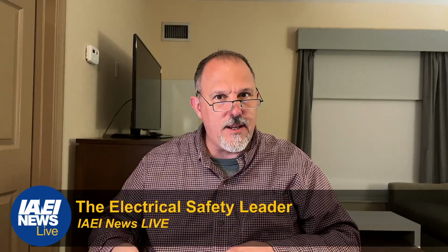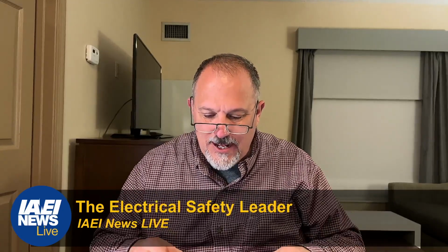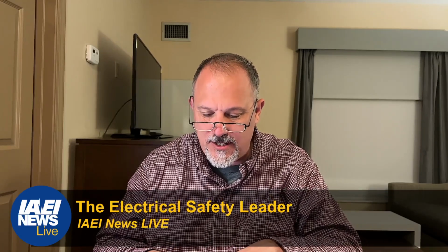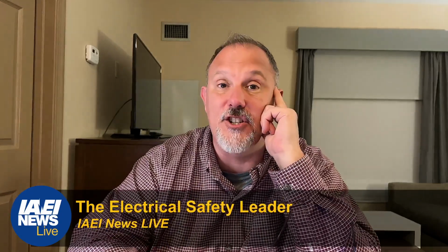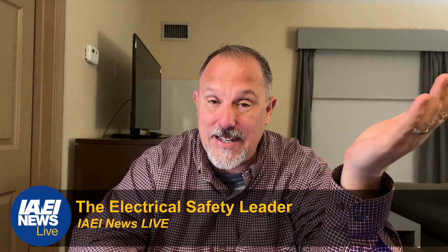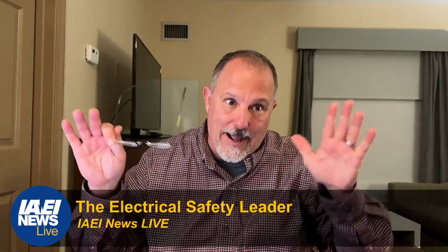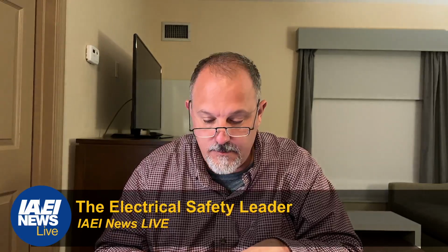Oh, this is interesting. If equipment supplied by an outlet covered under the requirements of this section is replaced, the outlet shall be supplied with GFCI protection. A receptacle outlet is an outlet. A hardwired outlet is an outlet. It's just dawning on me at this moment, how do I handle changing out equipment that is cord and plug connected on the outside?